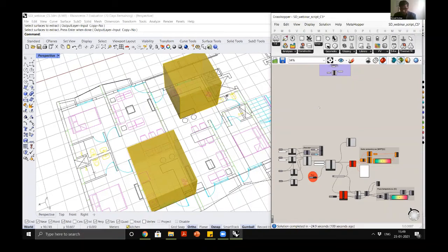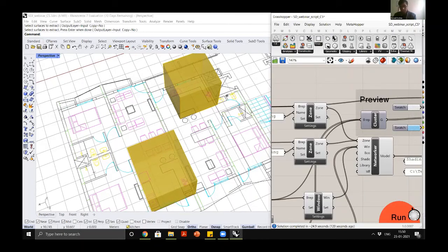You can check out this script. I'm not very sure about using it in Solar Decathlon because it's fairly complex. But still, you can look at Solemma's website for the tutorial on spatial thermal comfort. But for thermal comfort, as per Indian standard, as per IMAC, you have to do some post processing to the outputs that you obtain from the simulation model. So I hope that the first question gets answered over there.